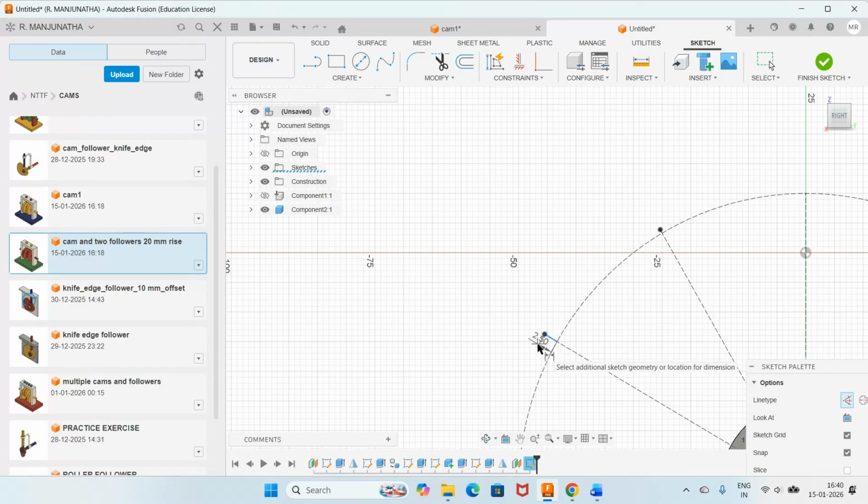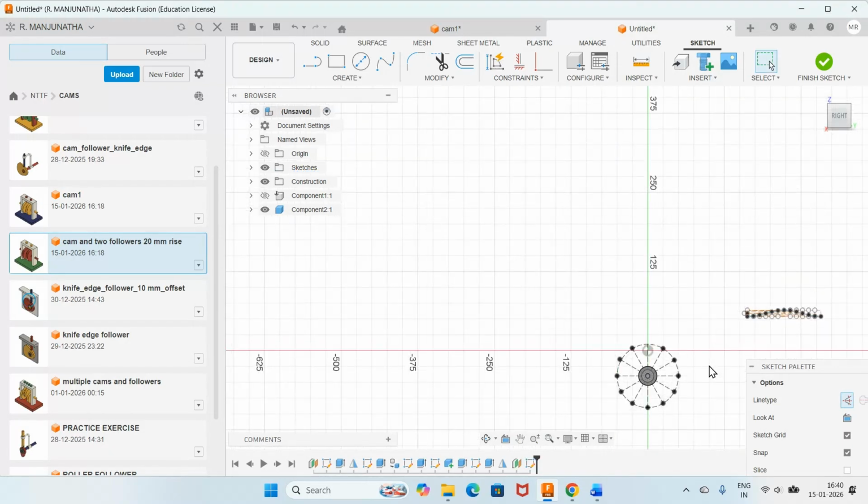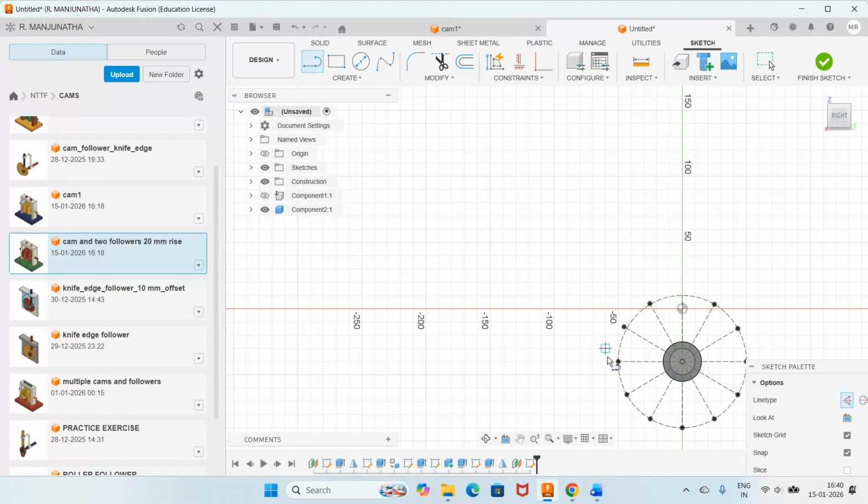Okay. The next thing is I want this vertical line, horizontal line. I will go for a line, select this horizontal line of any length. Go to dimension, select between these two, go to measure. And now you come down to fit and you come down to this line. So this will have 5 mm, enter.